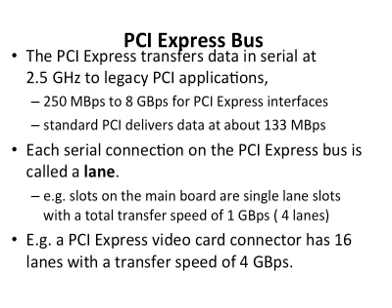For example, a main motherboard could have maybe 4 one-lane slots, and each lane transfers 250 megabytes per second. So overall, you can transfer 1 gigabyte per second with those 4 lanes. Another example, a modern video card may have 16 lanes, which can transfer data at a speed of 4 gigabytes per second.